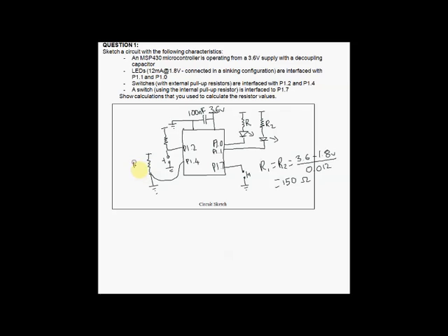Our pull-up resistors here should be between 10k and 100k, which allows us to pull up our pin, so we have enough current to be able to pull it up, but when we actually press our switch, our pin won't be shorted. And one little mistake I found over here, we should have actually had our switch in there and not just a ground connection.